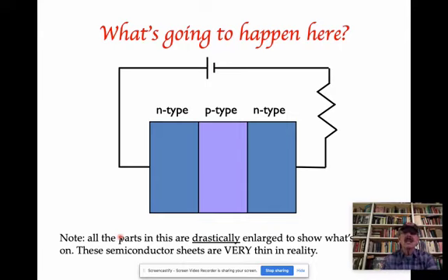So if you look at this device, what you see is an N and a P-type semiconductor together. So here's a little diode, and an N and a P-type semiconductor. So here's another diode that are basically back to back with one another. And I might add, in the real device that we're going to be discussing here, this section would be wafer thin. I've made it big so you can see it. In any case, if you think about this, you would probably conclude that this would be a pretty useless device.